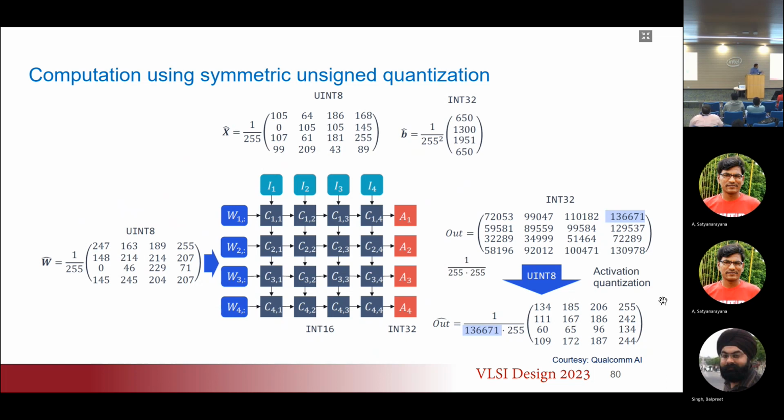So let's just say that in this case, the tile can fit 4 Ws and 4 inputs. This is one possible hardware implementation where I can multiply using this kind of structure, where each element is basically a multiply and accumulate unit. I apply the weight and I keep shifting through, and then eventually I'll be able to produce this result over a period of 5 clock cycles, 4 shifts, and then producing the result.